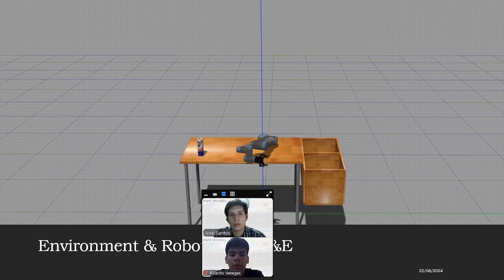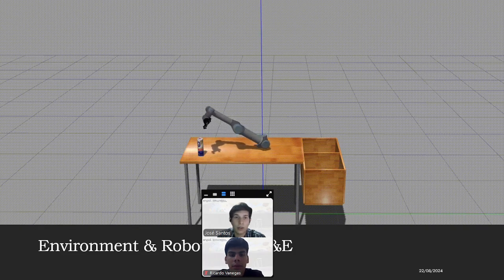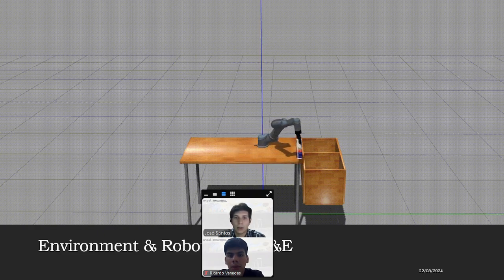First, we thought that we were getting the wrong angles from the Robotics Toolbox library, but in our presentation we noticed that the reference system is different between RViz and Gazebo. That's why the arm goes to the wrong position. So we need to convert from one to another when we want to achieve another goal.